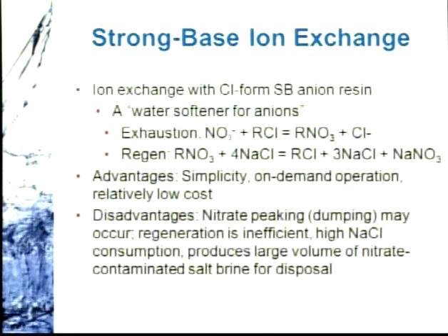So strong base anion exchange uses anion resins operated in a chloride form, typically. I'm not going to talk about bicarbonate form resins here. When you start out, you've got nitrate that replaces one of those functional groups that's holding onto a chloride. The nitrate sticks to that functional group, and then the chloride is released into the treated water. Regeneration just pushes it back the other direction, where you have a really, really high concentration of chloride that, from a concentration gradient, displaces those nitrate anions because of the concentration pressure. Then you displace that nitrate and put a chloride back onto the functional group. It's fairly simple.